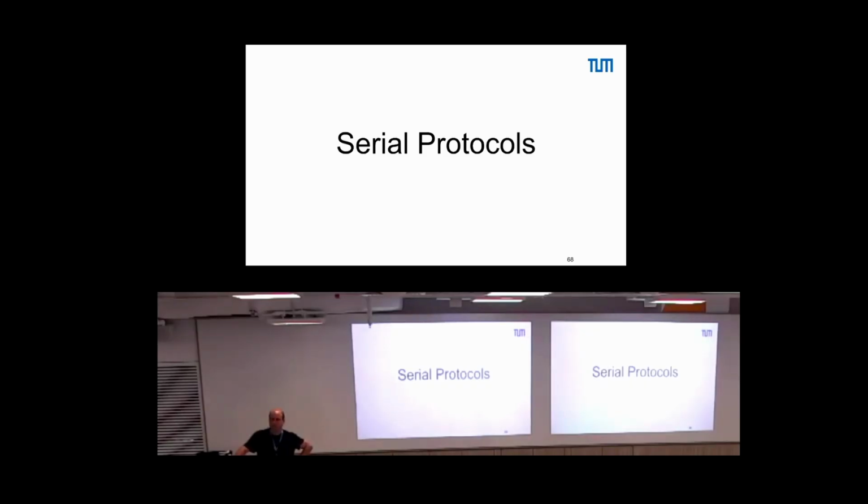So UART is from all these protocols we talked about the only asynchronous one. And therefore, it requires sampling in order to synchronize, to get the data correct and so on. Then if we think about the SPI, yes, it's full duplex. We have send and receive at the same time, and we have a master-slave system.